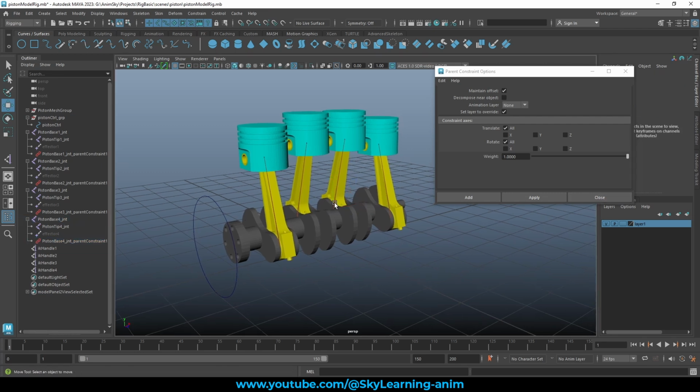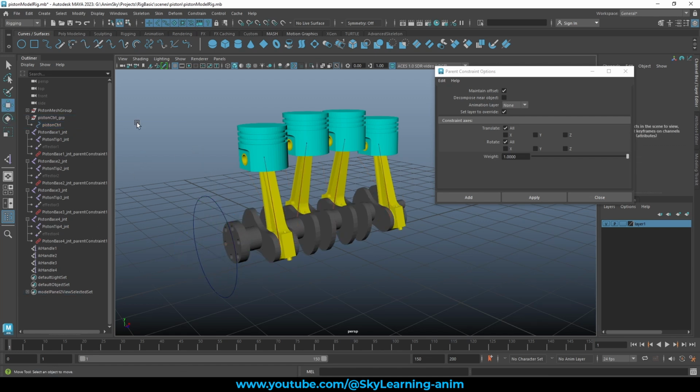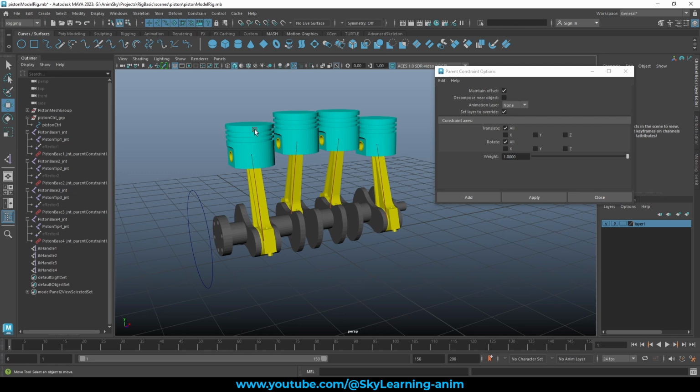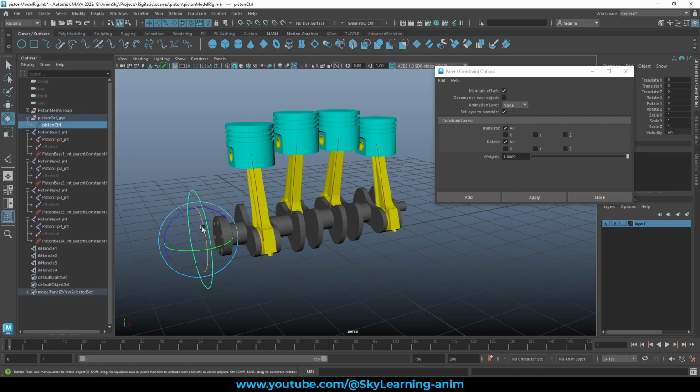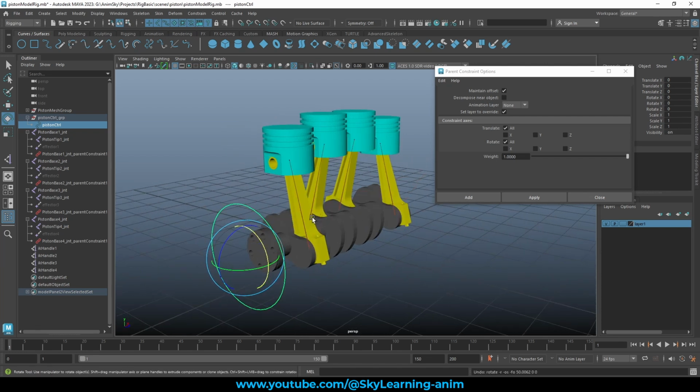So it's time we overview what we have done till now. We just gonna rotate in its x-axis, and we're gonna see our joints are moving with it. This is exactly what we wanted. So now what we're gonna do, we need 4 locators on top of the 4 cylinders, which will orient and keep track in the positive y-axis direction. Right now, if you rotate this and check, all joints are acting as pure children. We don't need them to act like pure children, just partially. The base only should be rotating, but the tip should always be aimed towards the positive y.